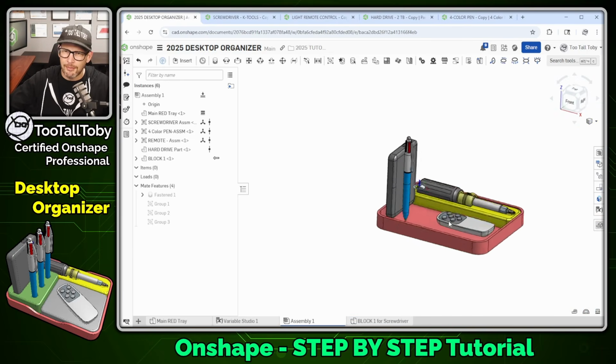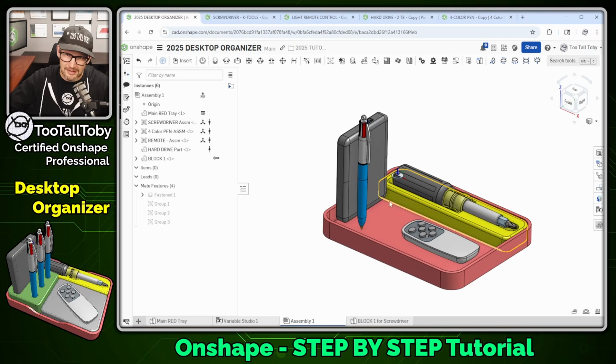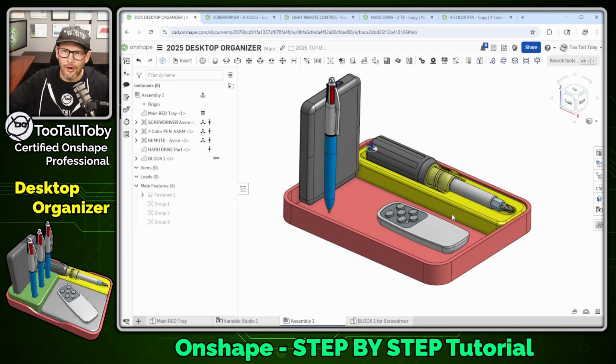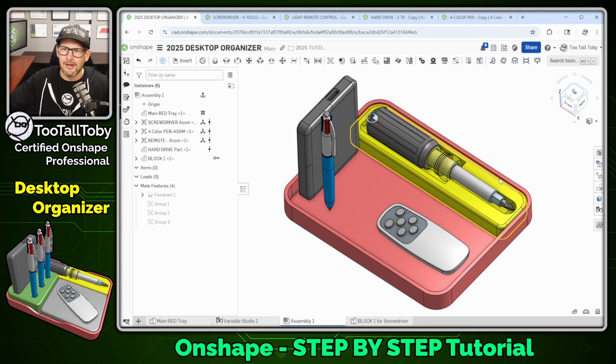Now, in the next couple of sections, we're going to see some other ways that we can reference the geometry from the assembly. Tools like doing a Boolean subtract with offset faces, or tools like doing an exact trace using intersect once again, but maybe using intersect with an offset, or tools like using surface offsets. So we will get into those in the next video, but this was really kind of the heart of this video, getting through and creating that first block.